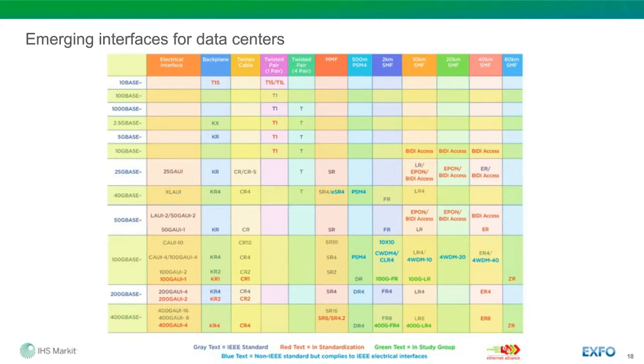and not necessarily within the data center, but also a bit shorter reach, allow for high volume 400 gig deployment, new technologies like DR4, 4 times parallel fibers, new proposals like 400 gig FR4 single fiber, 4 times 100 gig CWDM, and even a new one not even on the table, 100 gig DR1. So a lot of movement in that area.